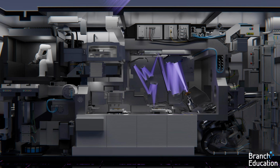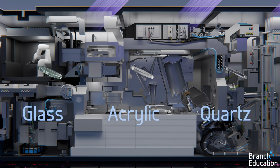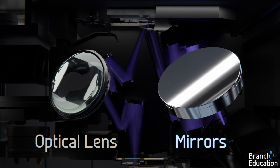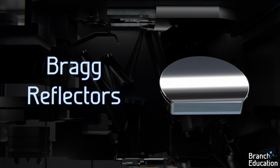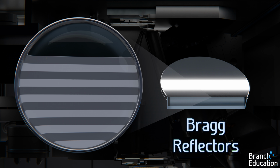Additionally, EUV light is absorbed by glass and practically all other materials, and therefore to focus and transport the light, this system uses mirrors rather than transmissive lenses. However, these mirrors, called Bragg reflectors, are nothing like the mirrors in your bathroom, but rather they're composed of dozens of alternating layers of silicon and molybdenum, each only a few nanometers thick.